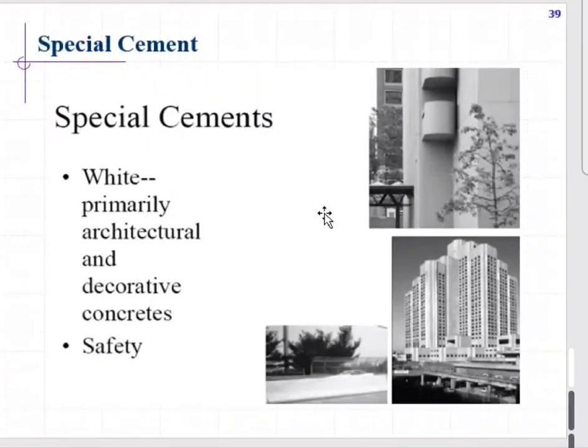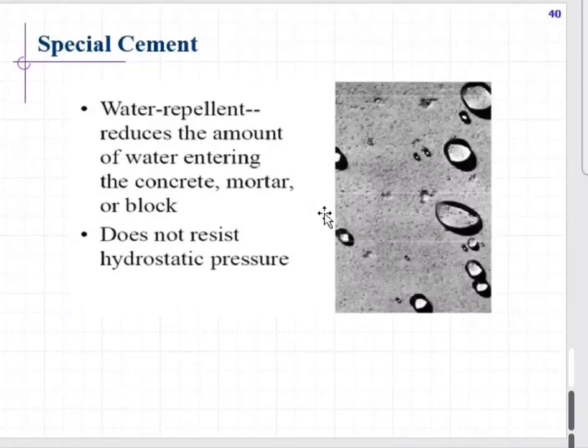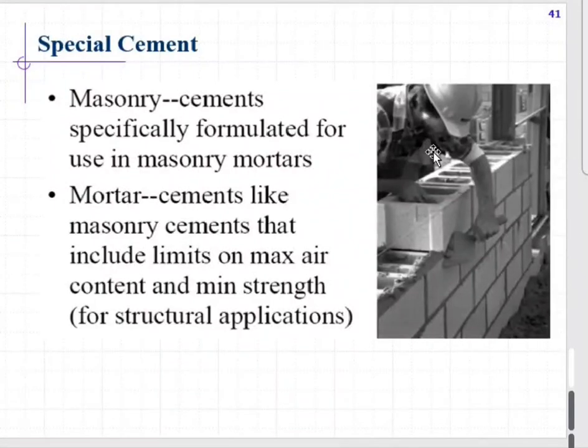Some special cements are there: white cements, primarily used for decoration or architectural work. Then water repellents are there. Water repellent means cement that can repel water and resist any kind of hydrostatic pressure. Then masonry units are there. You can use the mortar cement.